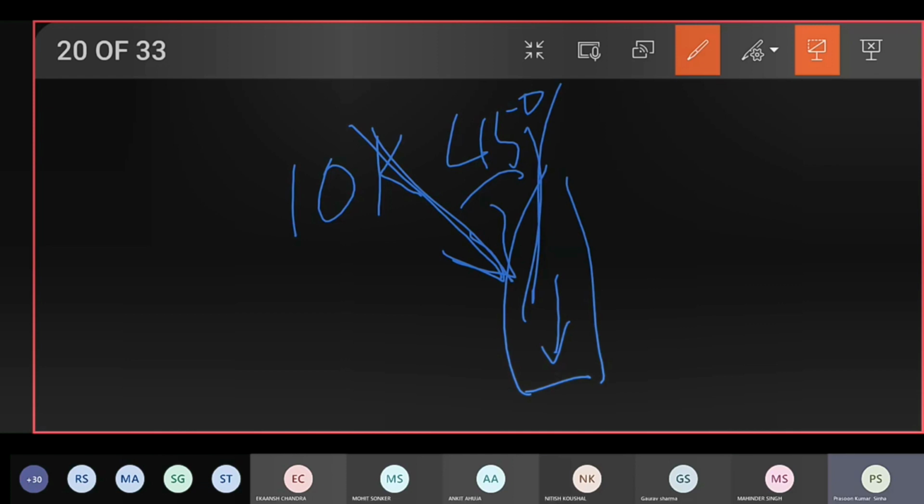We will not get the full speed. So another limitation is that it cannot read athwartship speed, and it will read only a component if it is at an angle. Two limitations. Number one, salinity of the water changes, the display has got an error.